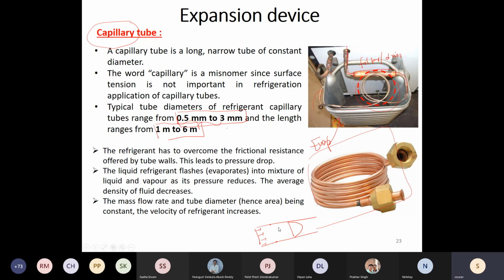You have to balance the continuity. Okay, and that happens across a length of the tube that is called the entry region. So you will not suddenly have the parabolic nature. You will have something of this nature, no? The velocity profiles, and finally it will turn out to be parabolic if it is laminar. So I'm discussing laminar flow. Okay, so all these phenomena will happen over here also, along with another phenomenon, which is phase change.